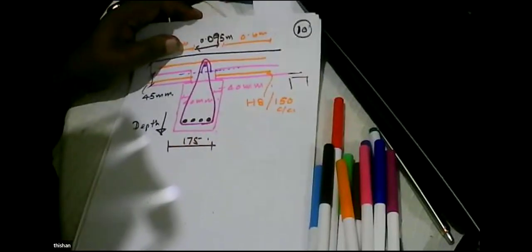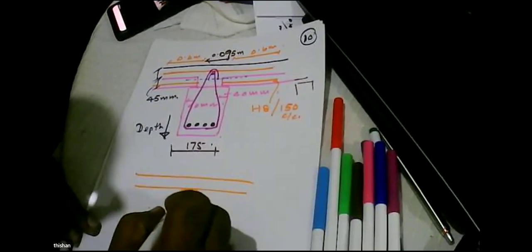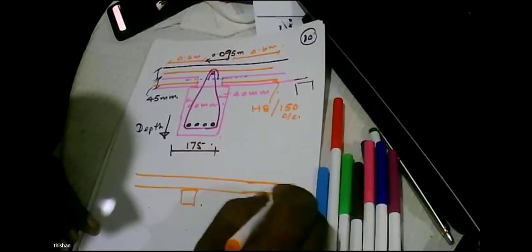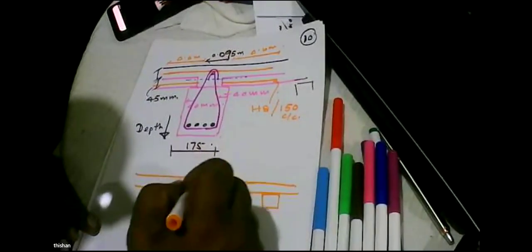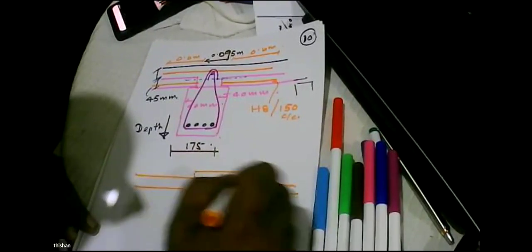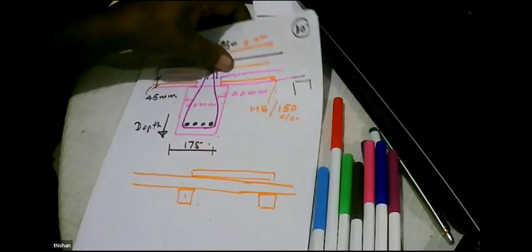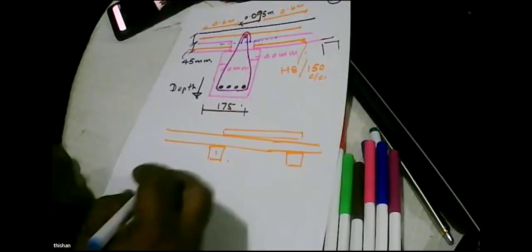Is there any special slab arrangement under the partition walls, either in X or Y direction? Actually, partition walls are not a problem at all. If you have a slab, beam, and another beam, and you are not sure of the slab capacity, the beam has to be designed for the partition load. We can have a small concrete lintel and do the partition. Then the loads will be transferred not onto the slab, but onto the beam.